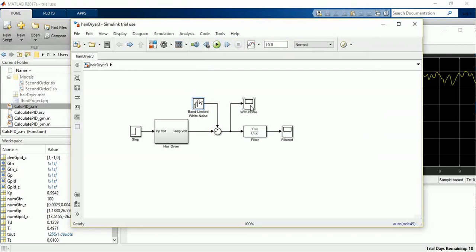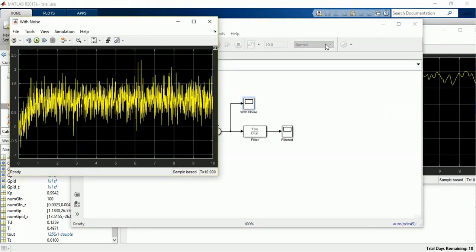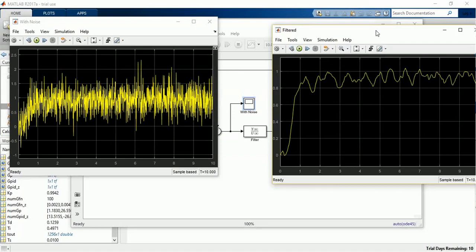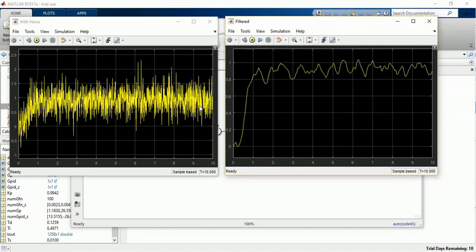I just want to see here the scope. If we compare both solutions, the noisy signal and the filtered one, we can see the improvement. But now that we have this filter, and we like this filter, the idea is to see how the open loop transfer function has changed, and what happened to the stability margins when we include this new filter. Let's take a look at that.